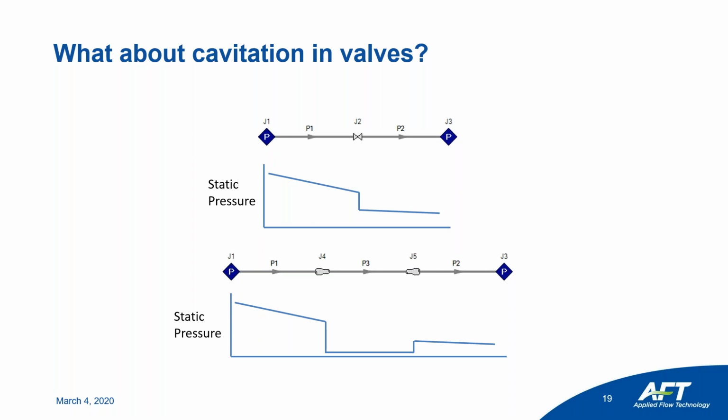You may be asking, why don't they have NPSHR for valves? Well, I don't think the damage is nearly as significant, and I think valves are not as expensive as pumps in most cases. And so I guess it's kind of an issue you just don't really talk about. But it's important to be aware of it.